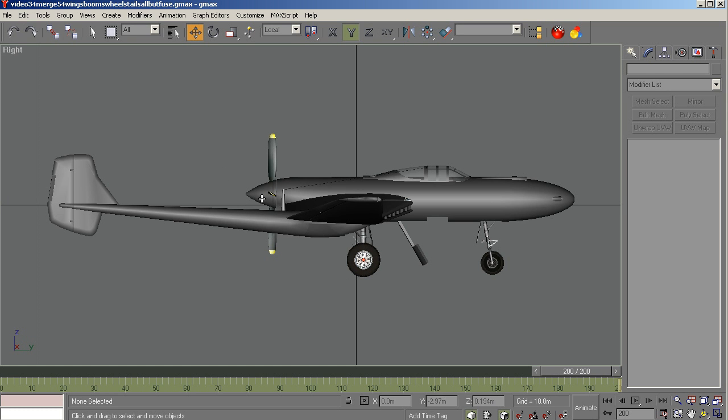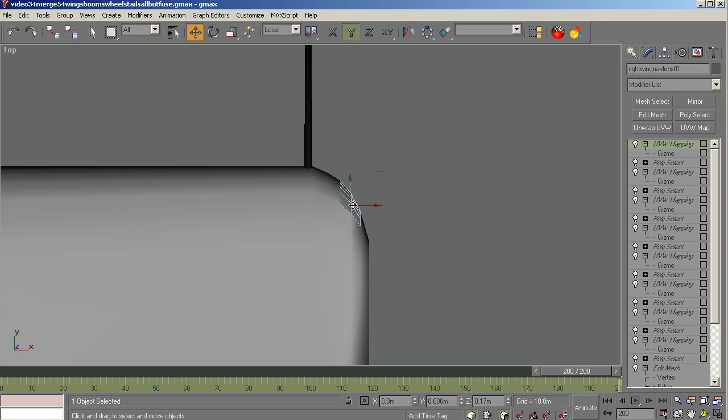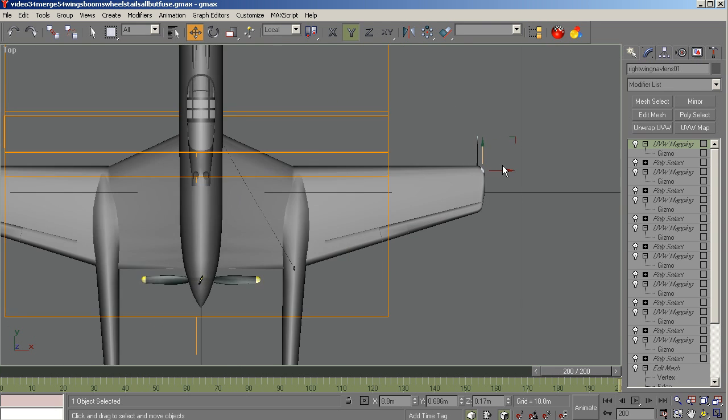We'll need things like your engine location. What it's really asking for in FS9 is what is your prop or your thrust location relative to the reference point. So we capture that data. Then of course we have wing lights. And why guess at it when you can go right here and click on this, and all of your coordinates are down here at the bottom. So we'll record those coordinates, convert them to feet, and update the sim with that.